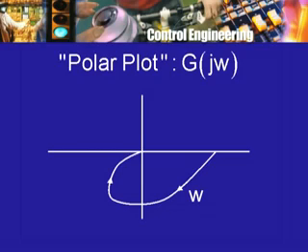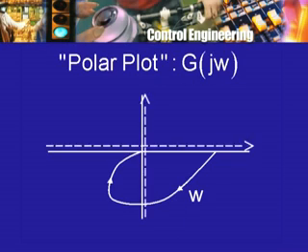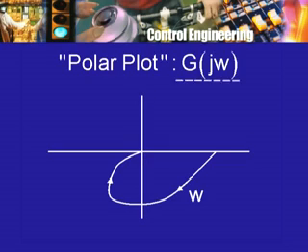And what we are now trying to develop is the following. Here is the complex plane in which there is a polar plot. As we saw earlier, the polar plot would depend on the number of poles and number of zeros of the system and their location and so forth. For the sake of simplicity, I am just drawing a simple curve, say a polar plot that looks like this. It could be just some arbitrary polar plot, it really does not matter. Each point of this curve is a value of G(j omega), that is, each point of this curve corresponds to a complex number. Remember, this is the complex plane, which is the complex number G(j omega).